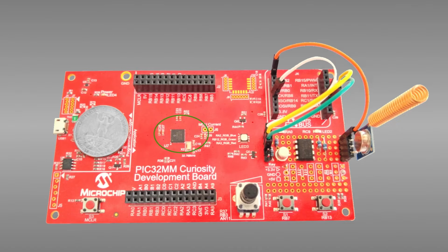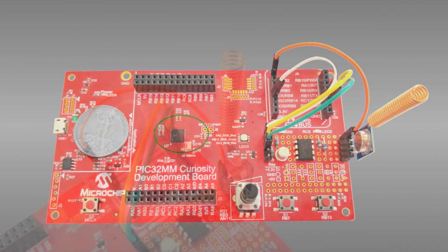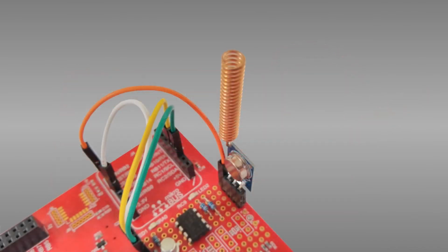Our key fob has 2 buttons, one for lock and one for unlock. The lock and unlock commands are transmitted by this little module here, which is a very simple 433 MHz AM transmitter, the very same technology used in garage door openers. This transmitter sends out information bit by bit at a rate of 2000 bits per second. This little transmitter is a module made for hobbyists. It will be much smaller in a production build.